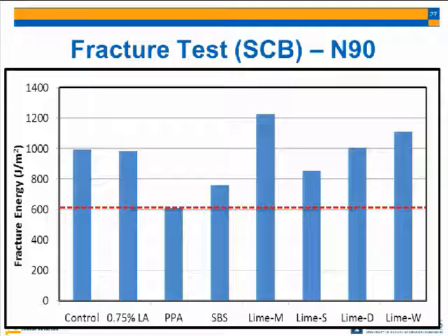I'm curious why you think this is going to somehow indicate any type of moisture susceptibility. The fracture energy. Yeah. Because we need to look at the low temperature cracking for Illinois, because we have this problem so much. So we don't want to end up choosing an additive or modifier which resolves the moisture susceptibility of the mix, but in the end increases the tendency of low temperature cracking in the field. So this isn't really an indicator for moisture susceptibility. Not directly. Okay.